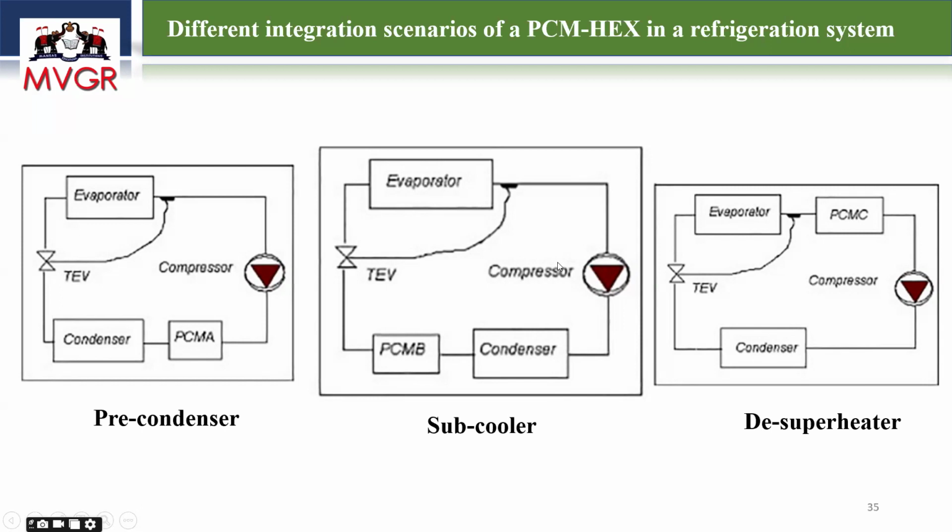Similarly, if you put phase change material after the condenser, some of the remaining heat will be absorbed, and the refrigerant is liquefied earlier, before entering the expansion device. A subcooling effect will happen, so that my refrigeration effect will increase. That will enhance your COP value.